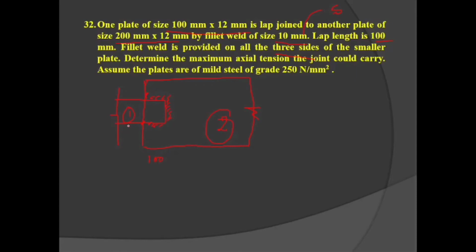This type of problem is generally a slot welding problem. Now the total length is given. What will be the effective length? We have to calculate the maximum axial tensile force, that is L effective into effective throat thickness into the permissible stress. But for that we have to calculate the effective length of the weld.